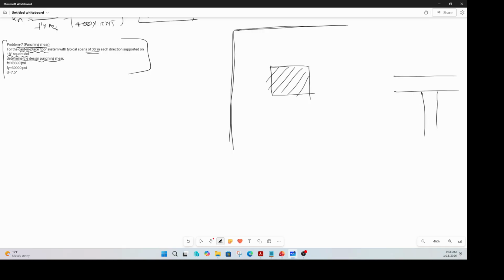Whenever it is a flat plate, it is something like this. Remember, a flat plate is like that, whereas a flat slab might have a drop panel like that. So the terminology should be clear. This can be either a drop panel or a shear cap. I'm talking about this piece. So this is a flat slab, whereas this one is a flat plate.